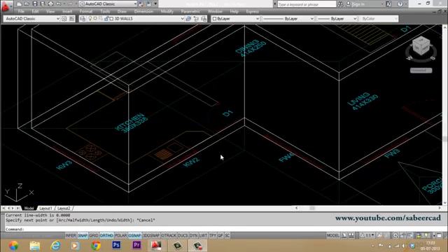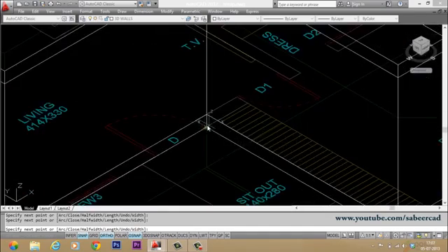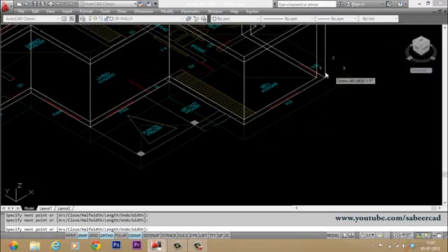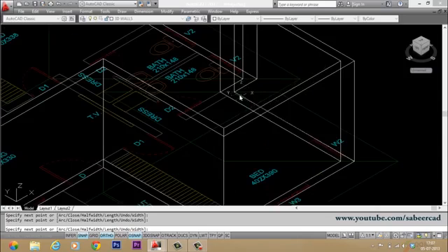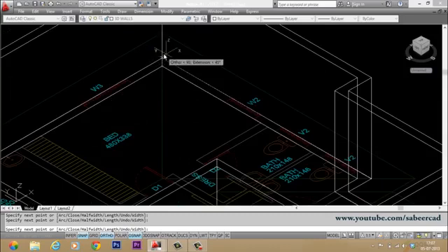Next we will create the doors and windows. But before we make these objects, we have to indicate the lintel level. You know that at the lintel level there is a beam which is running throughout, and that level is at a height of 210 centimeter, that is 7 feet from the floor level. So we will start with a polyline and I'll trace this line, that is a wall line. So I'll draw a line throughout. And I'll come back to this point and I'll give a close.